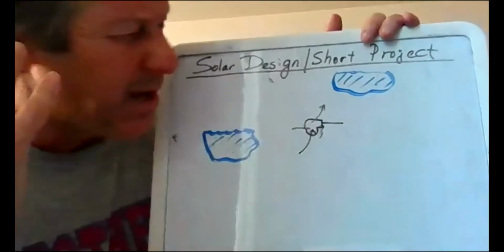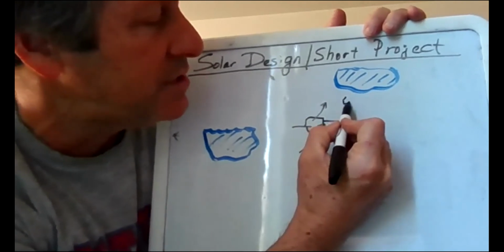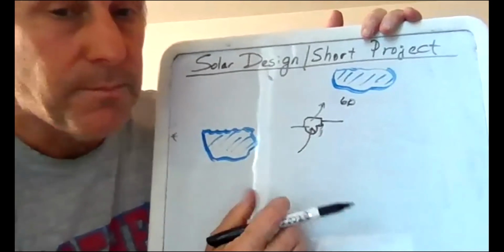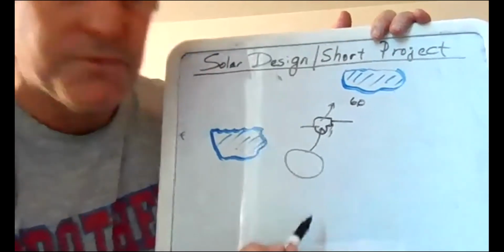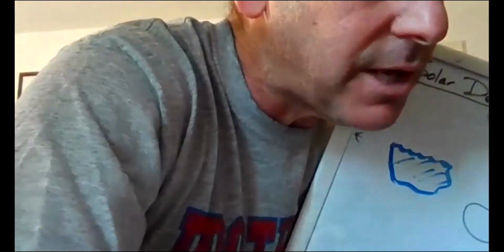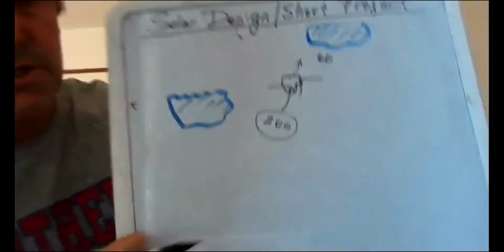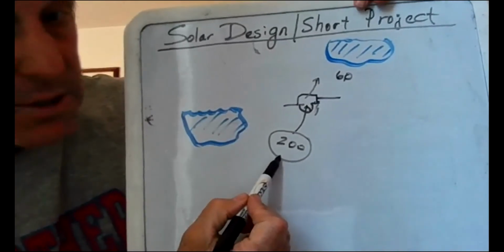So just making up some numbers, say 60 units of energy goes to the water, and the pump is 30% efficient. Well, it's going to take a lot more energy input to the pump. Pumps are usually more efficient than that, but I'm just going to do that really quickly. It turns out that I would need 200 units of energy into the pump. And then I could work backwards and say, where's that going to come from?